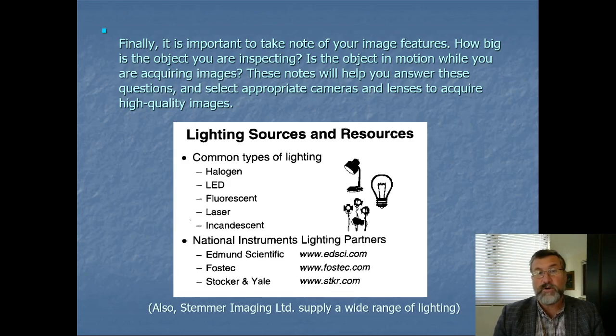But generally speaking, we're moving a lot away from that. And generally now, the lighting in machine vision is dominated by LEDs. There's a number of reasons for that, which I could go into in a bit more detail. The most obvious one is that LEDs are very flexible. You can turn them on and off quickly. They're very efficient, so they don't heat up so much, so it's not such a waste of resources. And they generally have long lives as well, compared to halogen lights.